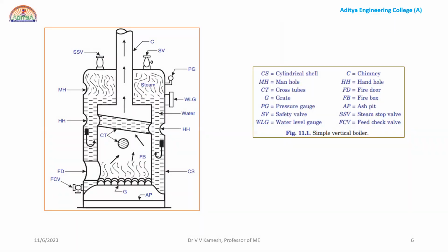Now coming to our vertical boiler. Any vertical boiler will occupy less space, and the furnace will be placed inside the boiler shell. To get the space advantage, the boiler shell will contain the fire and the water as well. Whether the tubes are fire tubes or water tubes, in the vertical boiler there will be a place advantage.